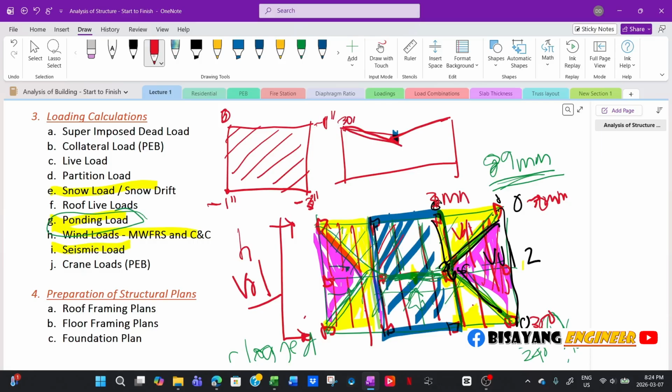And then in this particular area, it will look like this one. This is 30 millimeter, and then this is converted like 1 1/4 inch, and then this is I think 8 something. So whatever is the area, this will be your surface area, and then get the average height. So this one plus this one divide by two. So that's your total volume, and then times two because that's the same on this side.